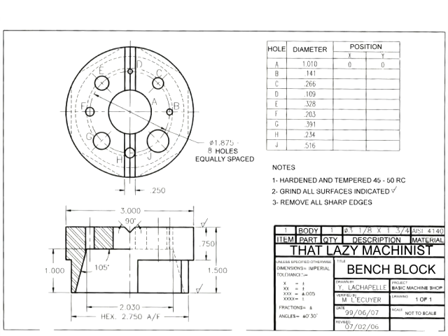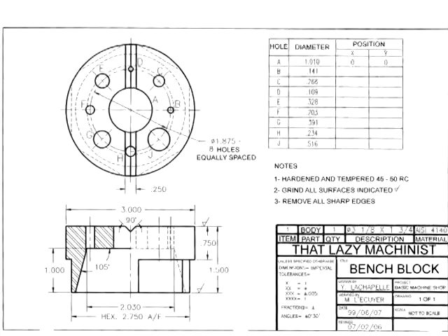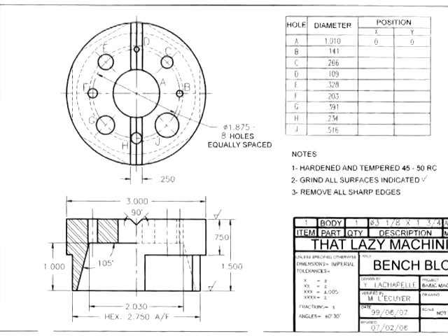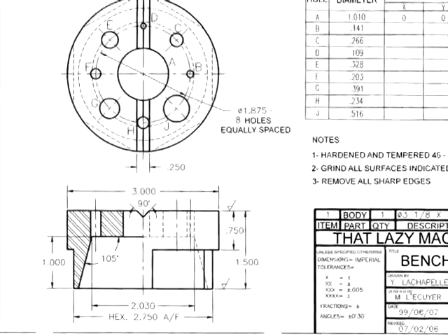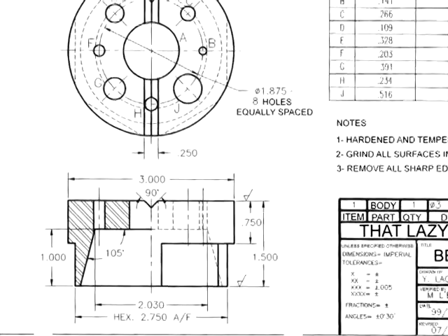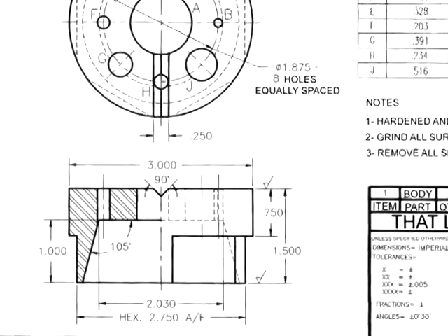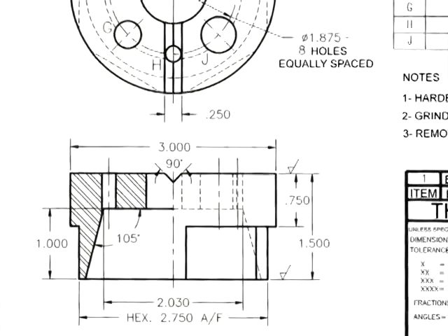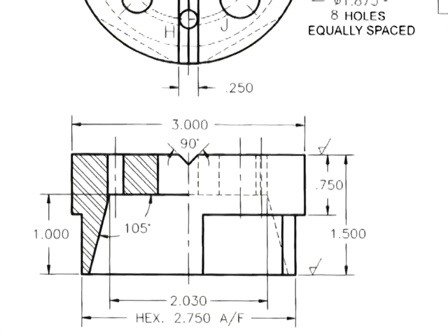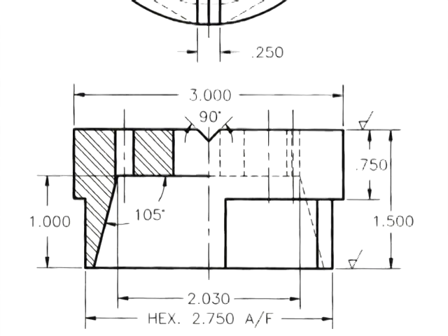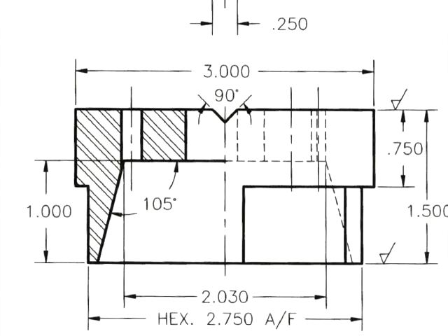One of the reasons for using section views is to eliminate clutter. Now, it's kind of like not seeing the forest because all the trees are in the way. Hidden lines and contour lines are important parts of a drawing, but sometimes there's just so many of them that they confuse things. And if we create a section, well, we eliminate a lot of them because obviously whatever is in front of the section isn't there anymore, and that's contour lines. And as a general rule, we do not show hidden lines that are behind a section view.